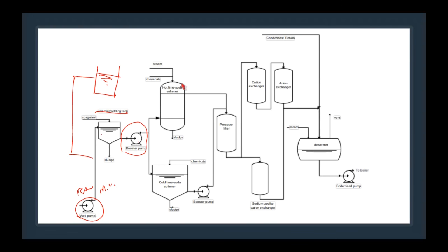Then we have some options too. Do we want to put it through a cold lime soda softener? Do we want to put it through hot lime softener? Do we maybe want to put it through a dealkalizer, followed by a decarbonator? Do we want to put the water through just a sodium zeolite softener?